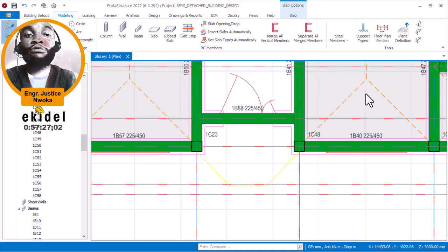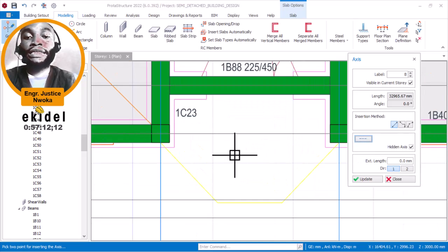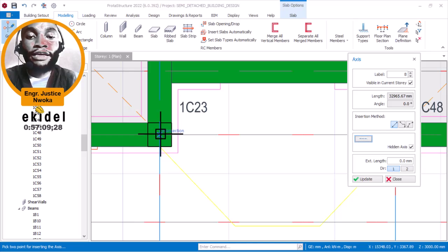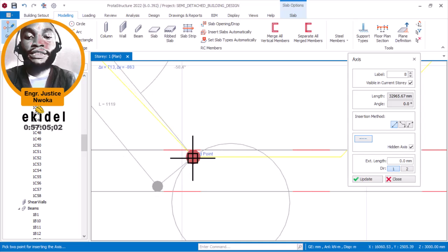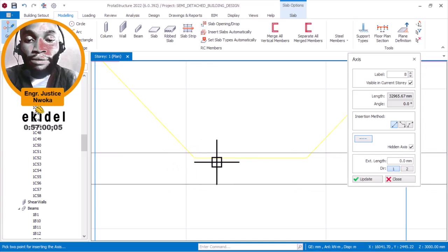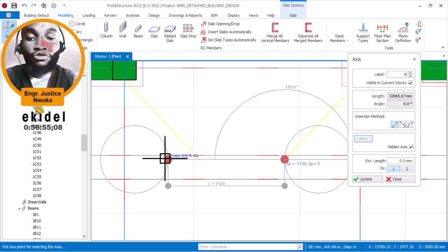So on the grid line now, I will convert it to ghost axis or hidden axis. Once that appears, I will move on to choosing my hidden axis here, and remove these bobs on my grid lines. And then I can go ahead. I want to begin my grid line from the center here and then come all the way down here. I want to get this horizontal one first, from here all the way, holding my control key to make the line straight, and click here.